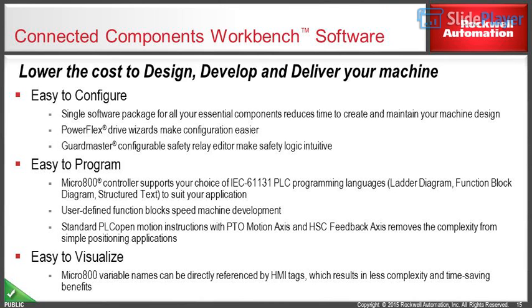Easy to program. The Micro800 controller supports your choice of IEC 61131 PLC programming languages: ladder diagram, function block diagram, structured text, to suit your application. User-defined function blocks speed machine development. Standard PLCopen motion instructions with PTO motion axis and HSC feedback axis remove the complexity from simple positioning applications. Easy to visualize. Micro800 variable names can be directly referenced by HMI tags, which results in less complexity and time-saving benefits.